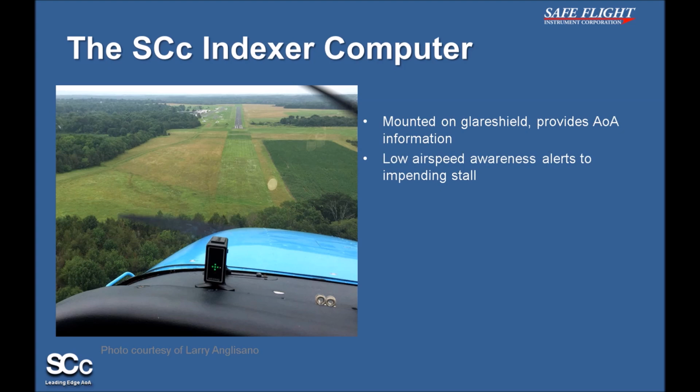The SCc also has a low airspeed awareness function that alerts the pilot to impending stall. In combination with the blinking amber LEDs associated with low speed awareness, the SCc has a Geiger counter-like audio warning as the AoA increases into the high AoA region approaching stall. This feature is also mutable, which is useful for low-speed flight training.